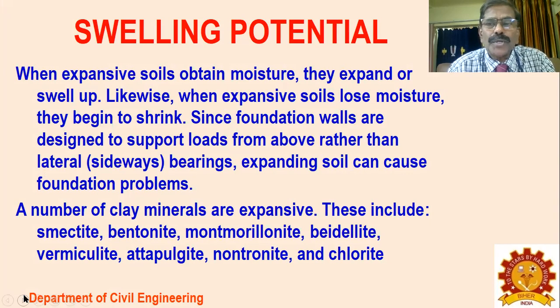So the swelling potential is, you can say, when the expansive soil obtains moisture, it expands or swells up. Likewise, when expansive soil loses moisture, it begins to shrink. Since foundation walls are designed to support loads from above rather than lateral sideways pressure, the expanding soil can cause us foundation problems. It's a common thing. So swelling potential is very important for expansive soils.